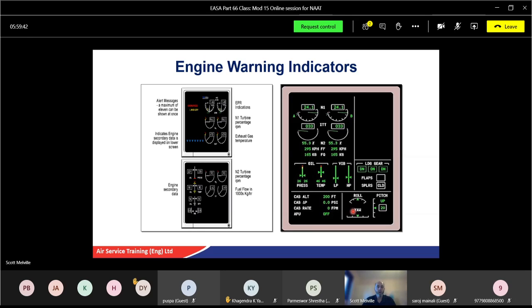So obviously the pump provides flow, and the more flow we get, the more pressure. My daughter used to laugh because I tried to teach her hydraulics, and she says no flow, no pressure. So if there's no flow, there's no pressure, and there's no indication on the indicator. The greater the RPM of the engine, the faster the pump is going, which means there's more flow. If there's more flow, then there'll be more pressure in the system.